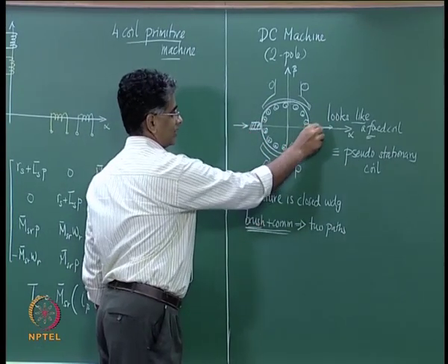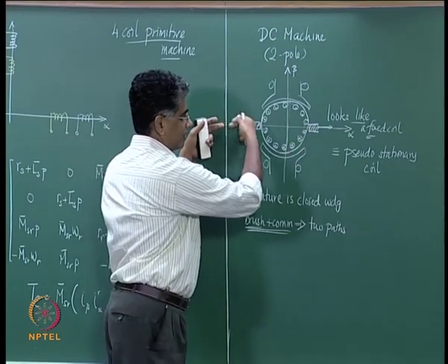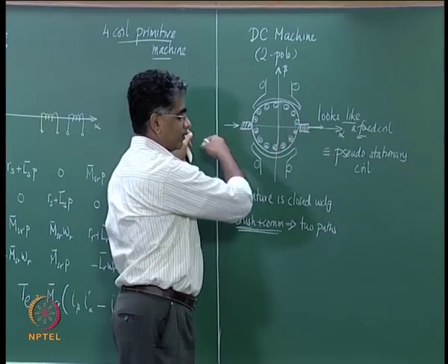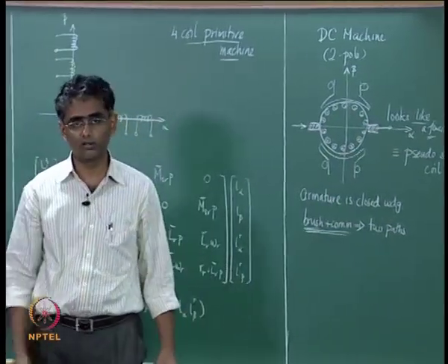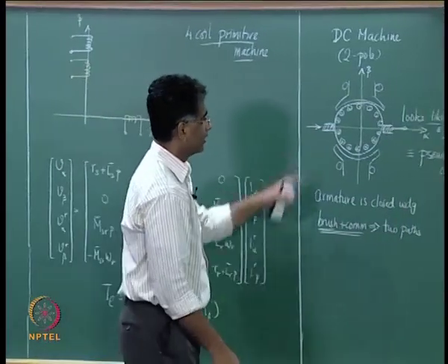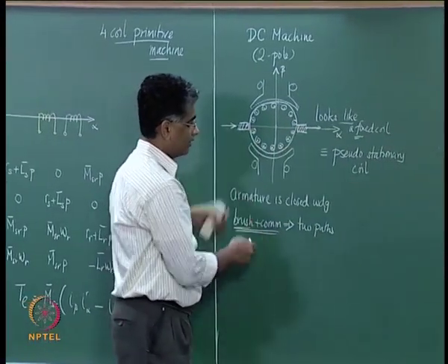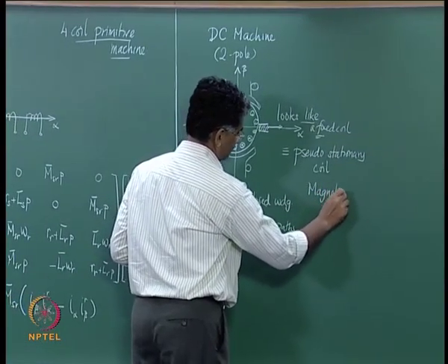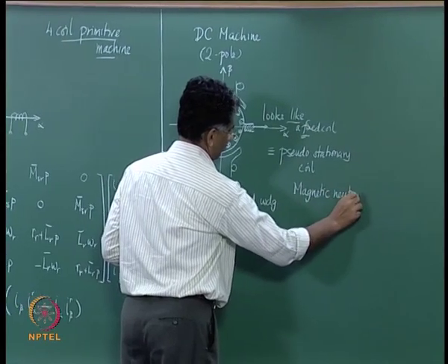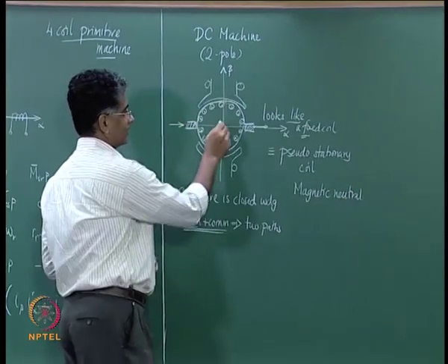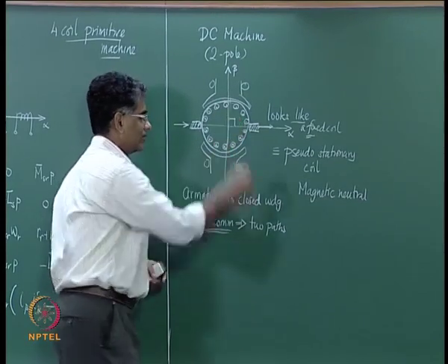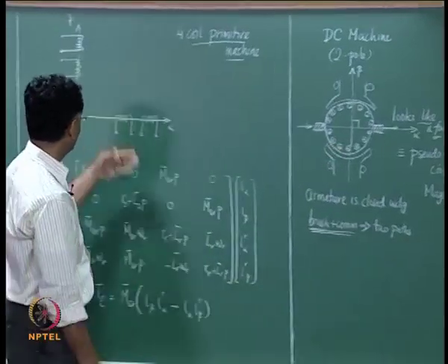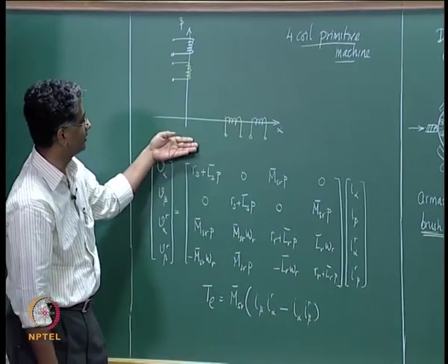That is going to depend upon where you are going to place this brush. If you place the brush here, then the armature MMF acts along this axis. If you alter the axis of the brush, then appropriately it acts along that axis. Normally these are then located on the magnetic neutral axis, which means that it is an axis that is going to be at 90 degrees to the field axis, which therefore means we again revert back to the same situation as we have seen here.